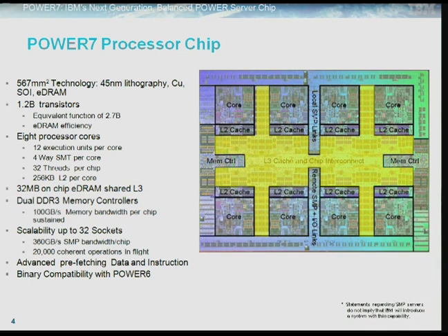There you can see the L3. The biggest advantage of bringing the L3 on chip is the latency reduction. Eliminating driver and receiver delays, the L3 on the Power 7 chip can be accessed in as little as 1/6 the number of cycles of the previous generation part.